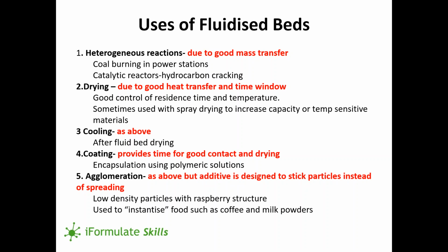Fluidized beds are also very good at drying. You get very good heat transfer like you do in a spray drying tower, but you also then have the benefit of a large time window. So you can dry particles over a long period of time and at a lower temperature, particularly useful for temperature sensitive materials.